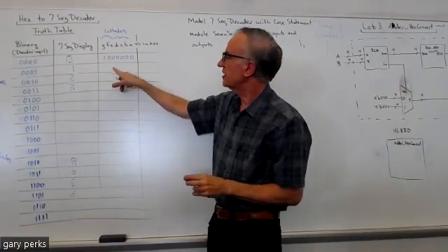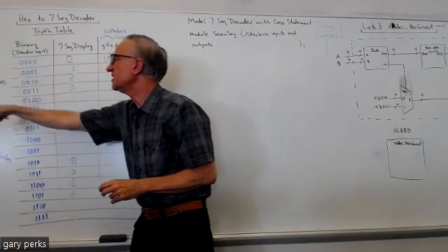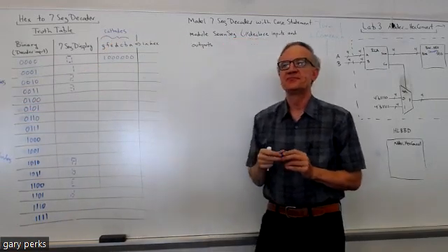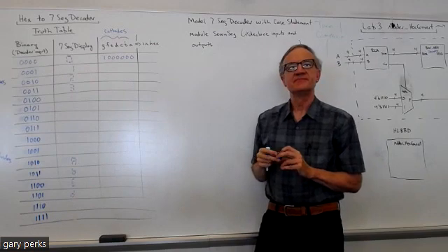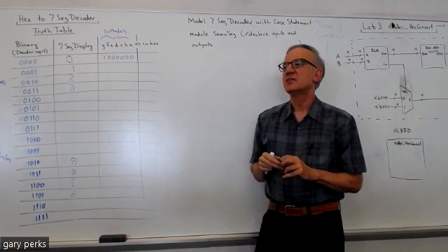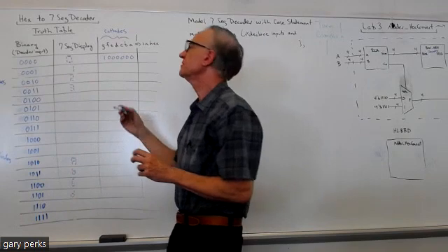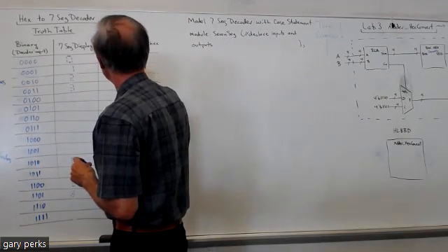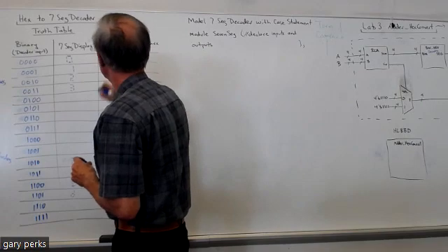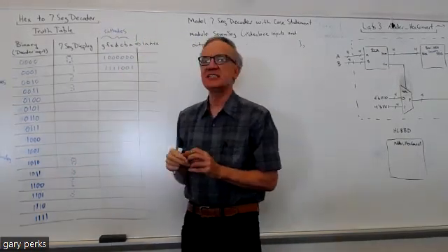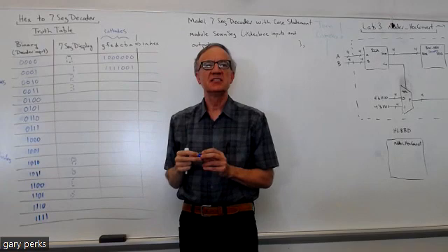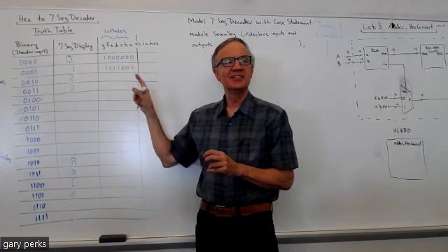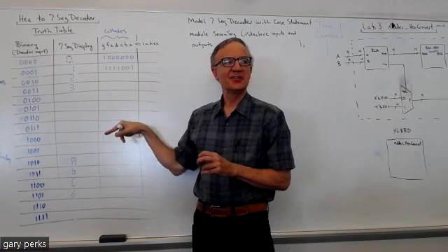Okay, how about to get a 1, which is B and C lit, what would you put here? Yeah, exactly. The only two that would be 0 are B and C, right? Everything else would be a 1. That's only going to light segments B and C. Do another one, or can you get the rest of the table?